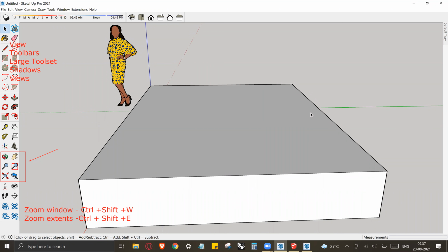All right. I'll do a quick recap of all the shortcuts, guys. Do pay attention. The orbit tool will allow you to move in three dimensions, a full 360 degrees, wherever around your model. The shortcut for this is the letter O only. To pan around, that is up, down, left, right, movement in a single plane, you see the icon is a hand symbol. That is why the shortcut by default is the letter H. And to do your normal zooming, it is the letter Z. Very straightforward, quite simple to remember.